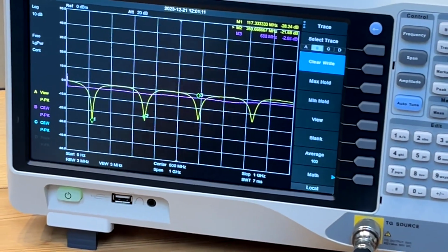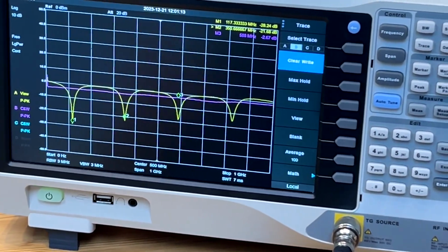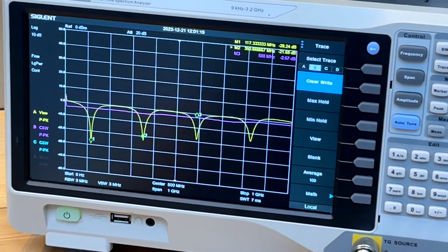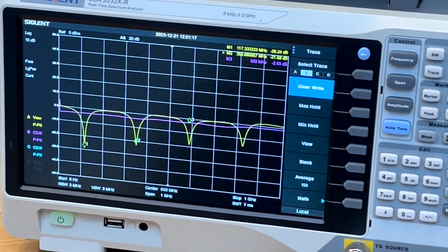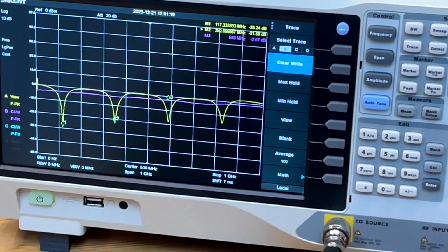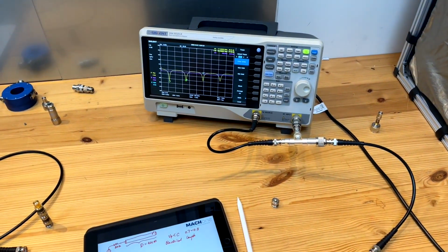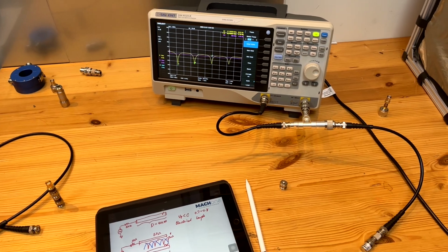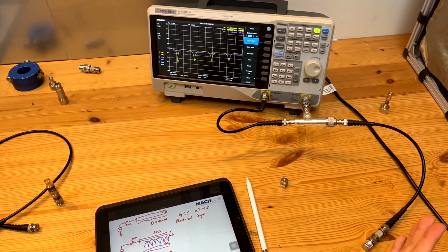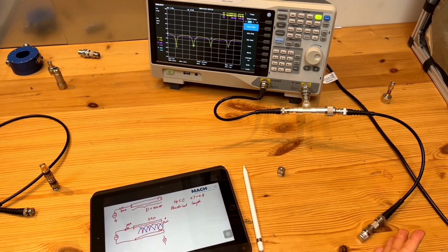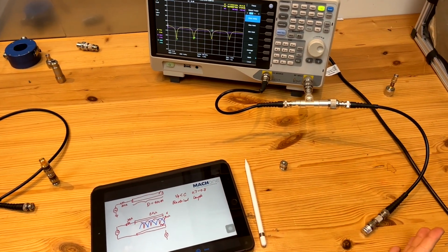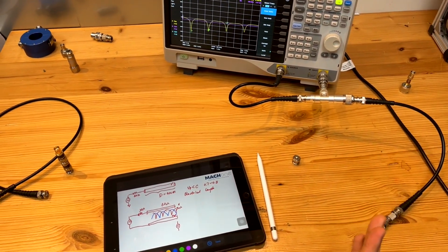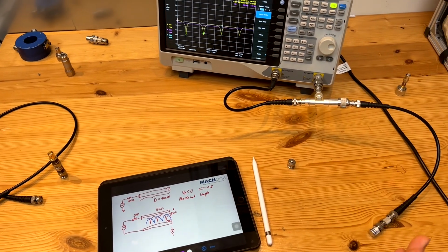So that's from the signal integrity point of view, something we want, and also from the EMC point of view, maybe that's also something we want. But bear in mind, all this discussion is inside the coaxial cable, so we can treat it as a differential mode here. But in most cases, as we know, you probably won't have an open circuit. You probably won't have a short circuit, and you will most likely never have a 50 ohm termination.